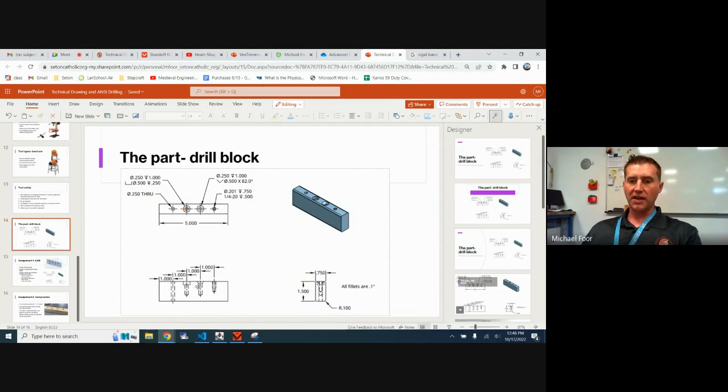Third one is a countersink. That's why it's angled. So it's a 0.25 inch drill bit down 1 inch. And then we have that 1/2 inch countersink. And then we have a tapped hole, and we'll kind of do these one at a time.